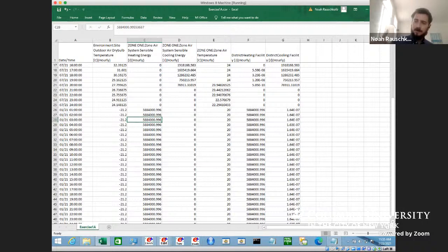You got to bring the materials in, create the window construction, define the vertices of the window, and then apply the construction, and that's how you add a window. So I think what I'd like to do is give you guys all 5 to 8 minutes to just try to follow through exercise 1B.